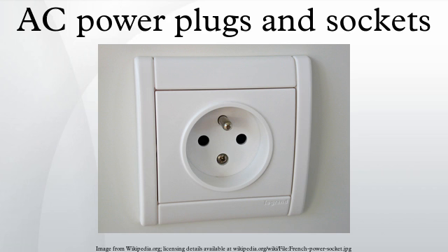The switch of the appliance is then connected in series with the energized wire. For an appliance such as a toaster, putting the exposed heating wires on the neutral side of the switch provides a small measure of extra protection against electrical shock. Similarly, lamps with Edison's screw bases will connect the screw shell of the lamp socket to the neutral conductor.